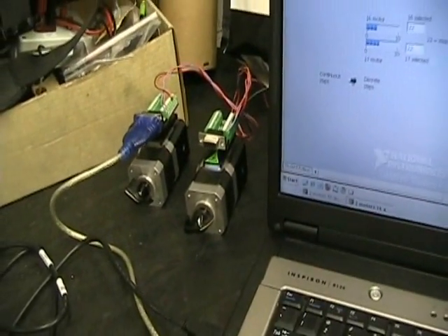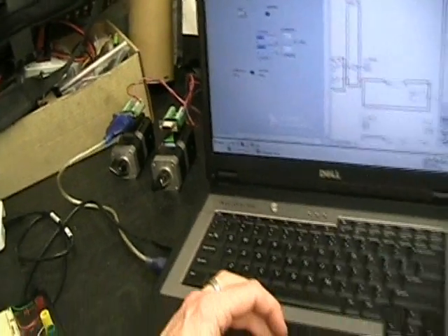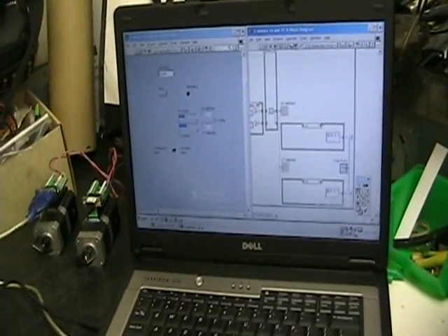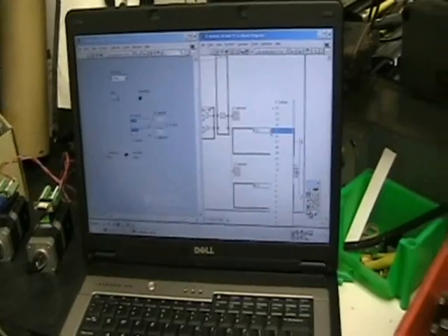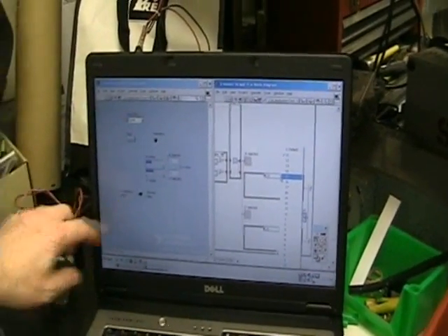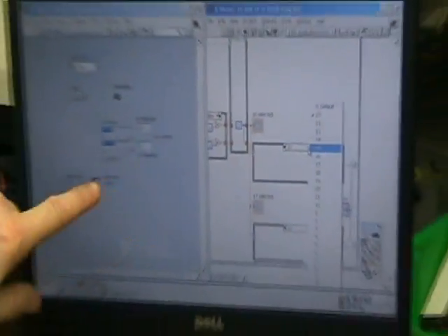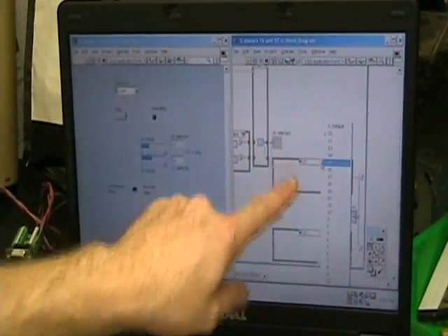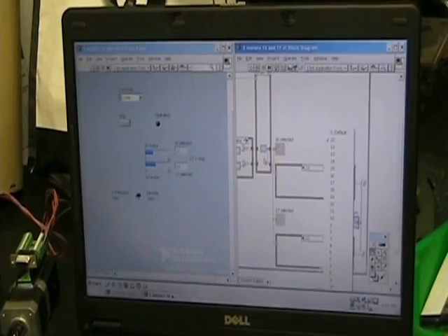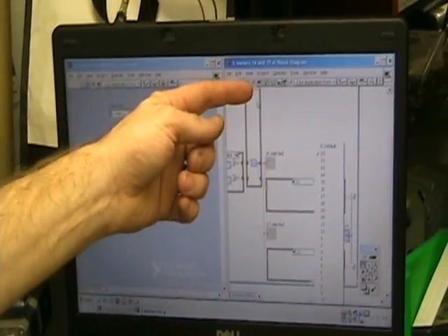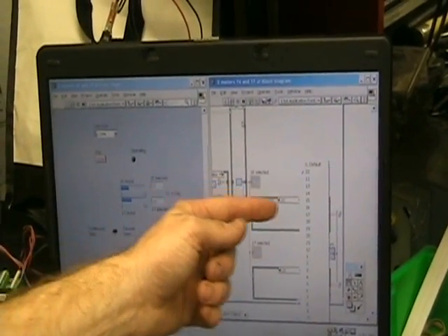And then we can look over here at what a 22 does. Okay, so here is a case structure. Let's pick this upper one. There are 22 different cases. Using the joystick basically gets to every single one of those between the joystick and this switch. It gets to all of them except for that 22. The stop command comes into this case structure and forces a 22 out.